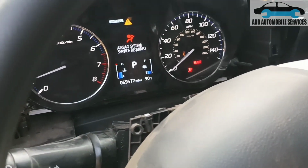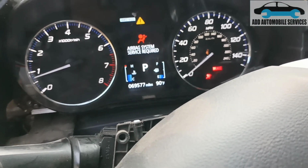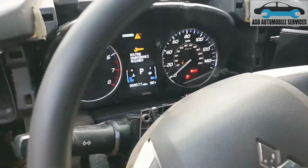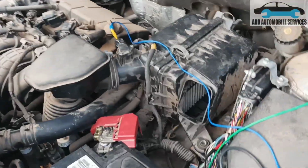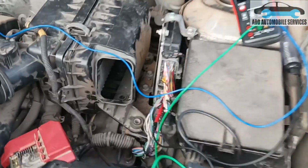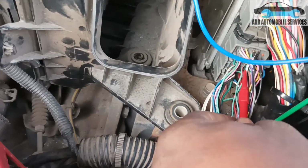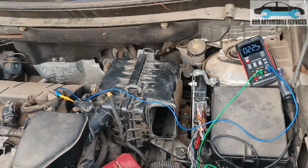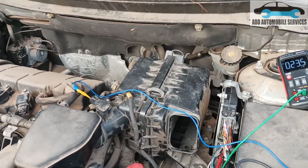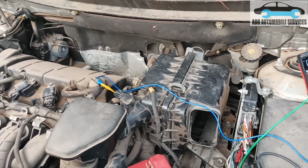And now still the RPM is really stable and the fault is gone. So with this one, it looks like it's a pin fitment issue. The moment I push this pin in properly, it gets contact, then you can see the engine is running and there is no fault code again.